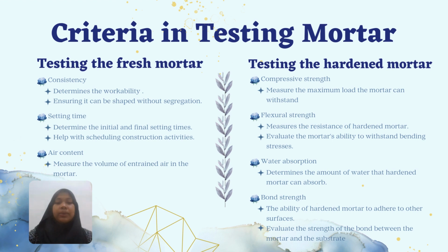Air content. The presence of air in fresh mortar can affect its workability, strength, and durability. Air content tests like the pressure or volumetric method measure the volume of entrained air in the mortar. The desired air content depends on the specific application and type of mortar used.